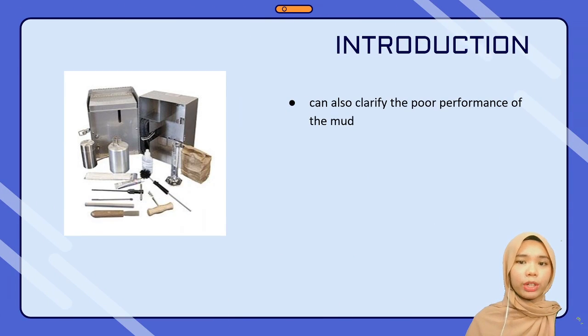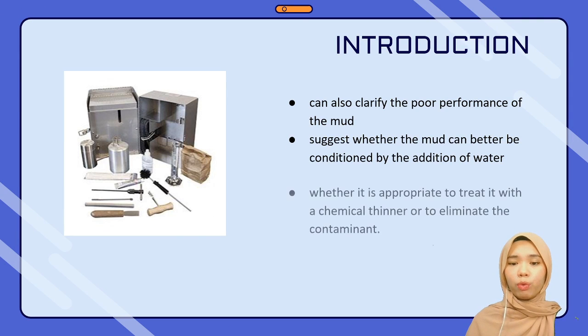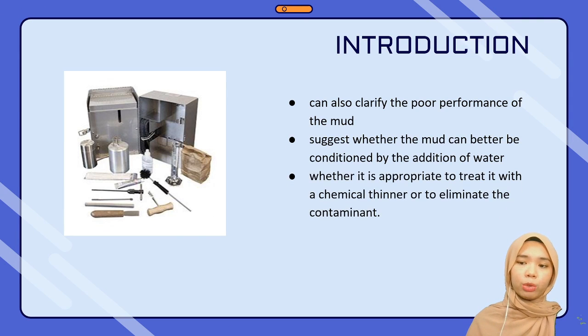This retort kit can also clarify the poor performance of the mud. It suggests whether the mud can better be conditioned by the addition of water, or whether it is appropriate to treat with a chemical cleaner or to eliminate the contaminant.